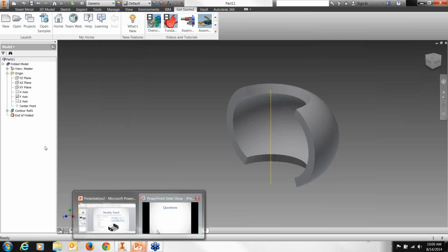See, there might be one or two more here. Is there a punch feature to create a stiffener in the L bracket? Again, you'd be leaving the sheet metal application and adding a feature that would have to be machined down if it was one solid, or added as a separate part and welded into placement.